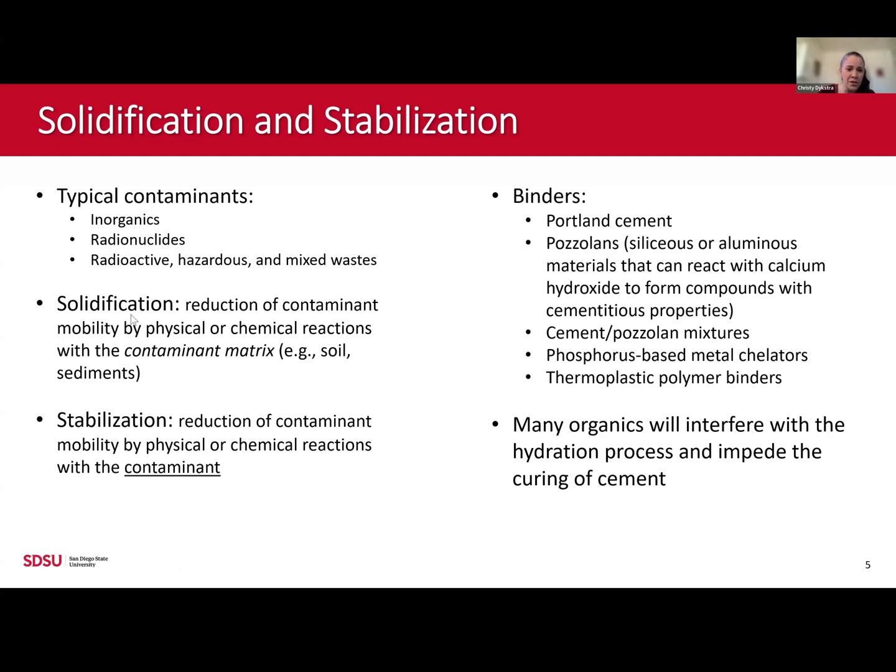So solidification, this is where we reduce the mobility of that contaminant by putting something into the environment that will react with the contaminant matrix, meaning if it's residing in the soil, what we put in is going to be reacting with the soil particles or the sediment itself, not necessarily with the contaminant.